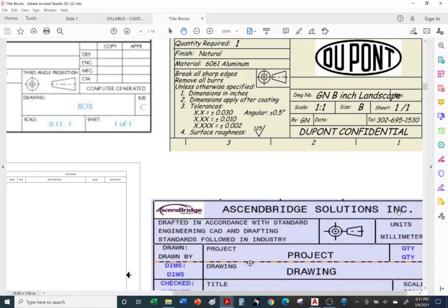You also have to call out the units. So 99% of your drawings in mechanical drafting will either be millimeters or inches. It's rare, but sometimes you will combine the units. One good example is you'll make your entire drawing using inches, but it just happens that the thread of the hardware that you had to order only came in millimeters. So it's okay to use a drawing all in inches, and you can call out in the drawing that the hardware is metric.